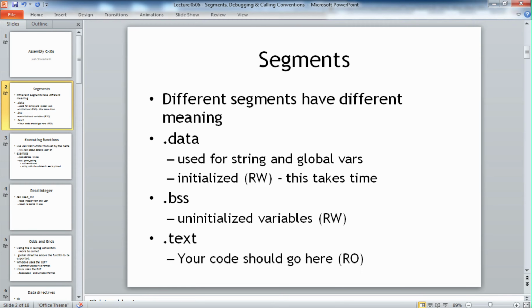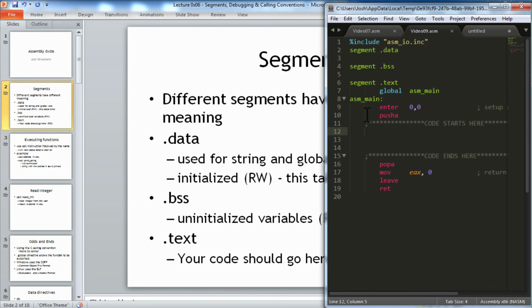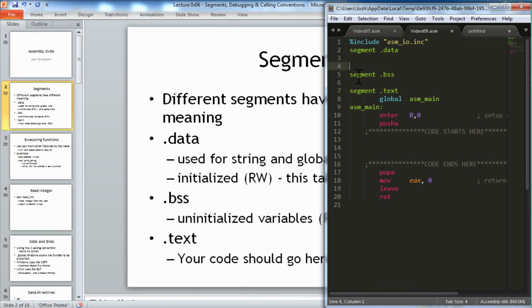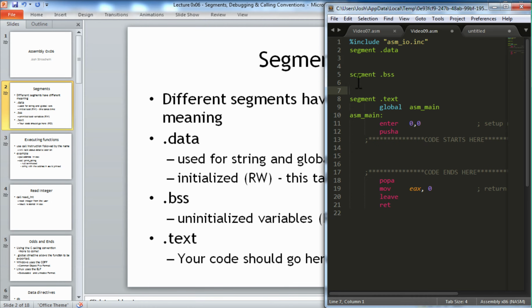And so as we're starting to create essentially variables, depending on their use, we're going to put them in the appropriate section. Initialized values will go here. Uninitialized values will go here, right? And if you're going to create a variable and you're going to set a value later on, then you might as well make it uninitialized because you're going to end up overwriting those memory locations anyway, right? So probably the biggest thing right now, as we go through examples today, is making sure that when you're starting to create these variables, you're putting them in the correct location.